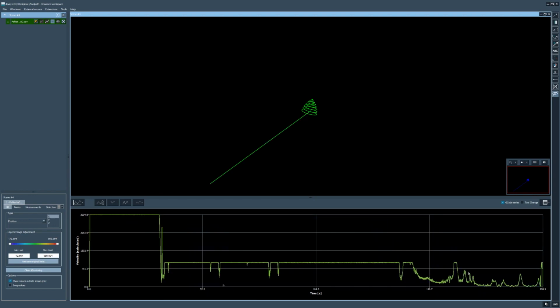I only want to see this area here where we have the feed rate of 1000. Let's hover with the mouse over here. Yeah, we see with the balloon tip what the values are. The first value is the X value, so that's 47.93 seconds, and the second value refers to the velocity, which is like 999, so nearly 1000. So let's select this.